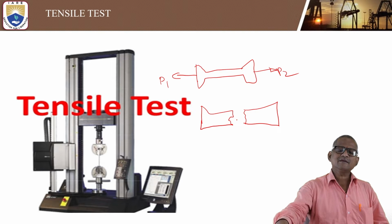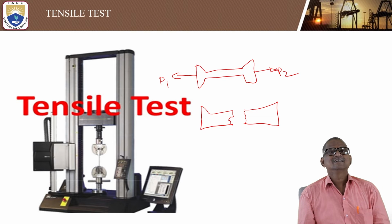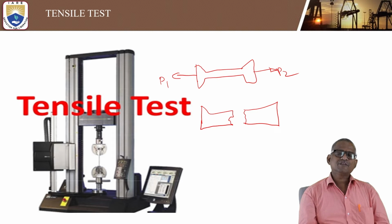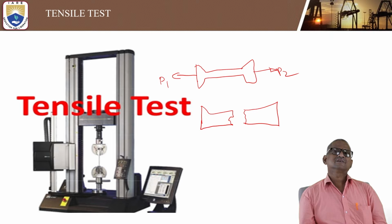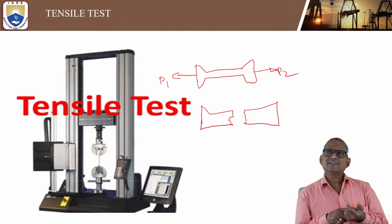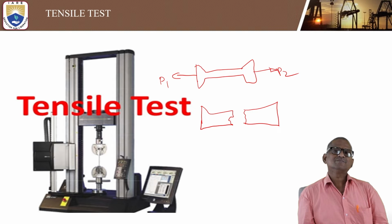So at that breaking point, we need to identify the hardness and the tensile strength that may be obtained. Like different cases, first case, second case, third case, then you can average it. In that way you are able to test the parameters. In general, in a destructive test, mechanical properties such as tensile strength, toughness, hardness, ductility and brittleness can be determined. All these tests come under the destructive test only.